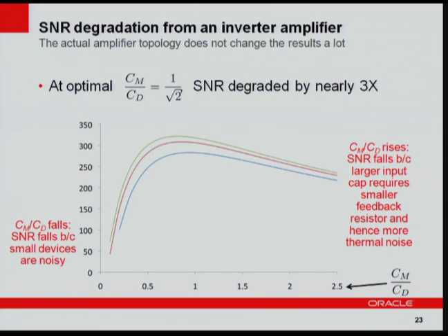Okay, so with the larger technology nodes, you get a slightly improved SNR. Sorry, this axis here is SNR. So if you recall the number that we had previously for the simple resistor receiver, we had an SNR of 750, huge, right? So we have decreased it maybe by a factor of 2.5 to 3 over here, simply by having that additional amplifier.